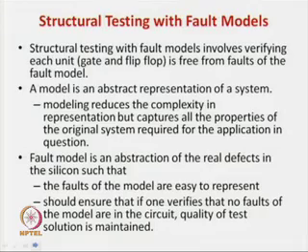So till now we have seen that functional testing is difficult because of the exponential number of test patterns, and structural testing is beneficial because it gives a very small number, k test patterns, much less than 2 to the power n, yet the accuracy is very high, as large as 99.9% plus. But the problem is the huge number of pinouts, and also there can be a large number of internal 2:1 multiplexers and registers. We have seen that by using registers we can save a lot of pins, but the number of registers was still the problem.